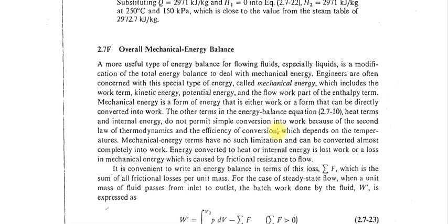So in fluid mechanics, generally we are solving the problem of fluid flow in a pipe. This is the simple flow, and the velocities are generally not very high, and the fluid is generally a liquid, water or air or any gas or any oil like crude oil, petrol, diesel in most industrial problems. In those problems, whenever you are solving this type of problem, generally you are not converting thermal energy to mechanical energy or other forms of energy into mechanical energy, and also you are not converting mechanical energy to other forms of energy to a large extent.